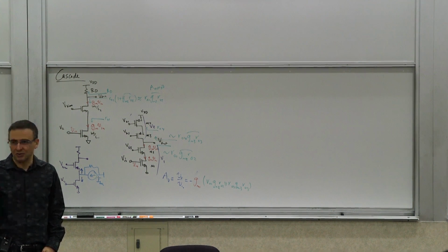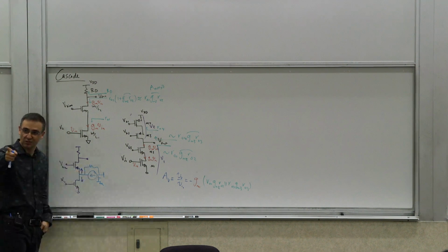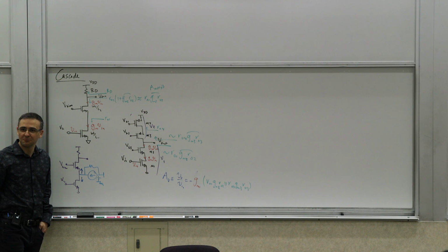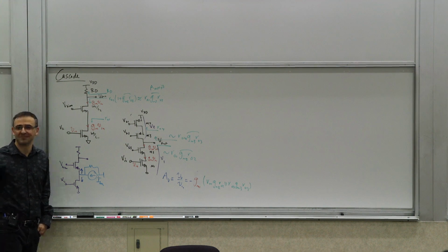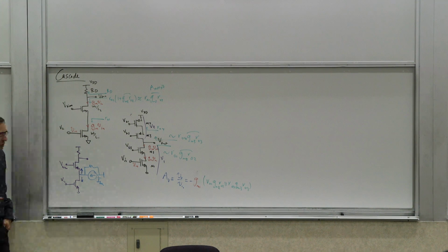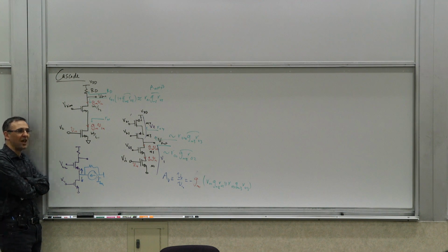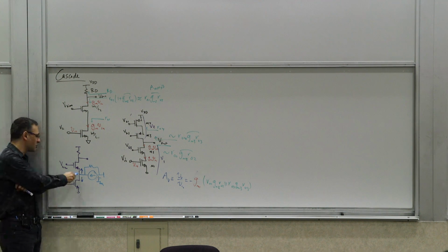The drain or the collector, right? The one with the highest impedance. So this is going to be the impedance. Going back to your question, which is a good question: how high is this resistor? It's an RO. RO-ish, or maybe higher, if you can make better current sources, which we will make. So this is an RO. Now, if this were an RO, would this be a problem for this node?